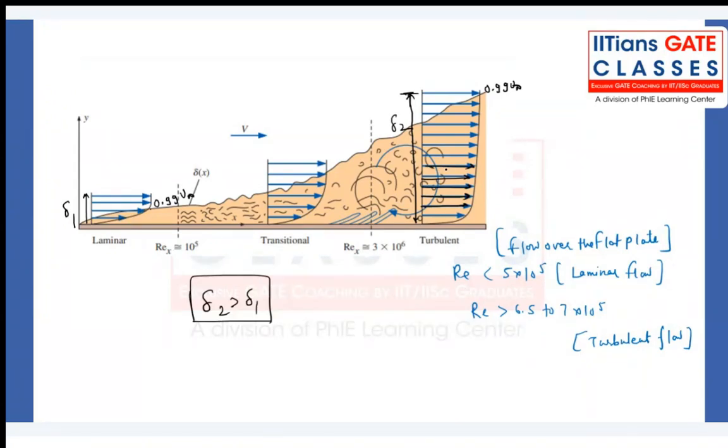Momentum transfer obviously will be there from one fluid layer to another, but the messenger, viscosity, which propagates the message from the wall, will also be rapidly shooting in the y direction among the fluid layers.